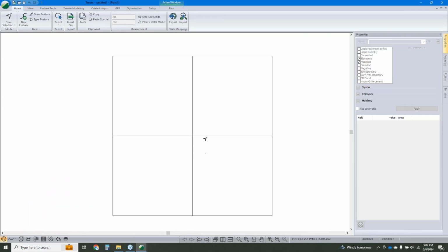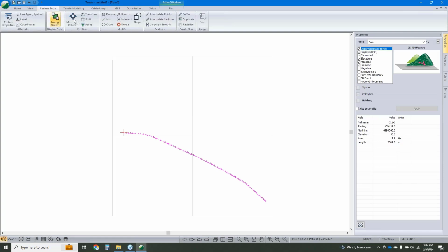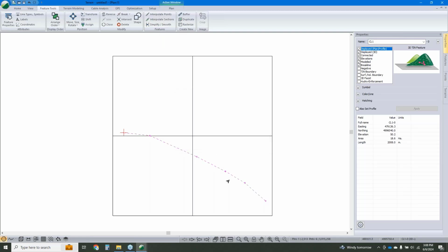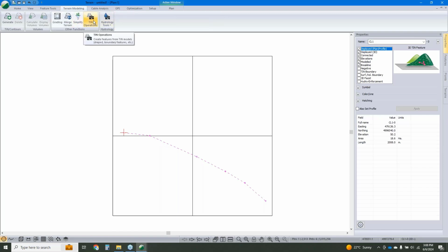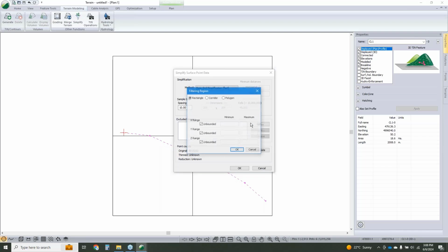So I'm going to just click off to the side. Now here we've got 5 million points in there. Reasonable amount to model. I'm going to reduce that though. So I'll take that surveyed center line that I copied from the one file, and I'm going to tell the software, well, I only want my LiDAR data within, say, 300 meters of that.